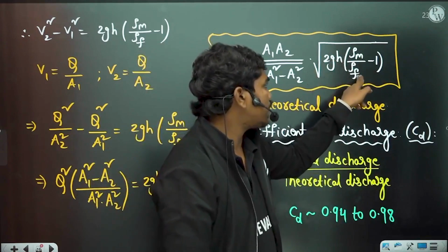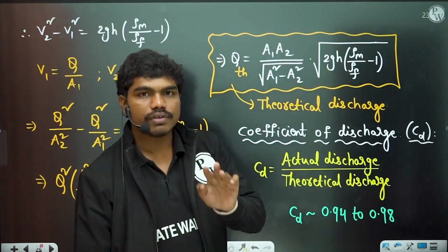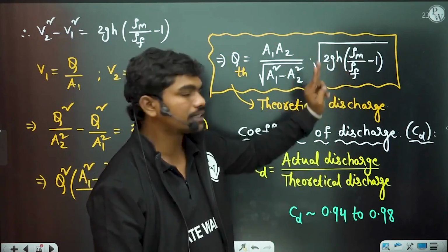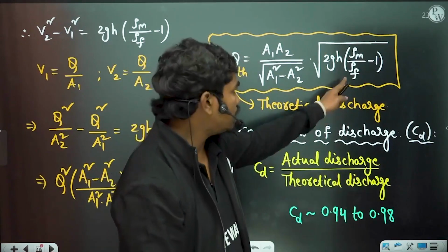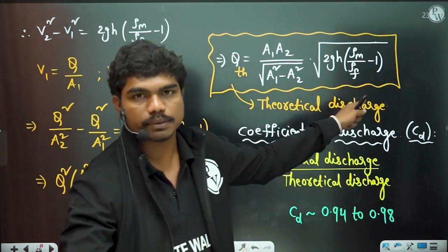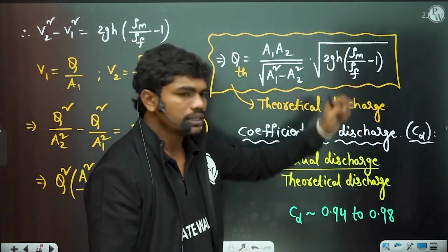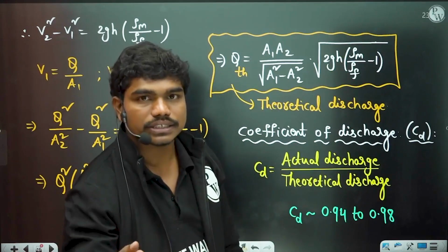If you change the fluid and the flow rate, this H actually changes. So we keep two columns empty for filling: one is density of fluid and one is H. If you are filling water, 1000 is fixed. If you are filling gasoline, as in diesel engine experiments, we will fill that in. We have very small Venturi meters also, to understand the flow in gasoline engines.